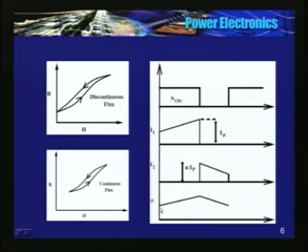So this is the variation of flux. Flux increases, it starts from a finite value. Mind you, this is at steady state, and then decreases. See, the secondary current has not become 0 prior to closing the switch. So when I close the switch here, this current is forced to become 0, and immediately the equivalent primary current starts flowing from here.